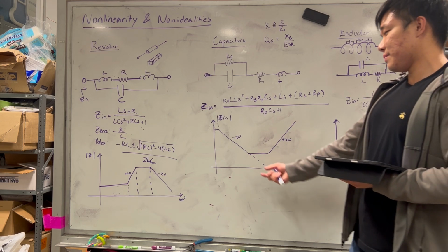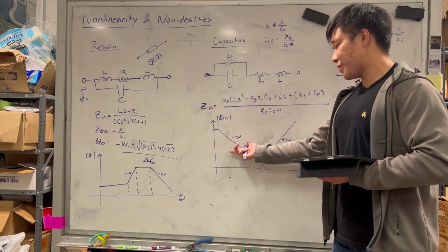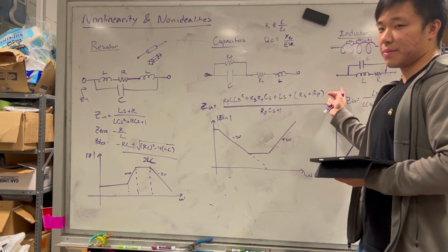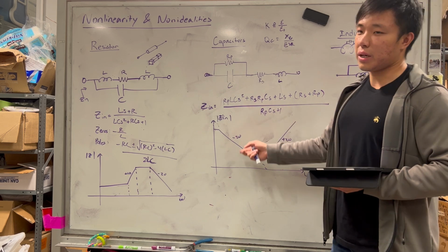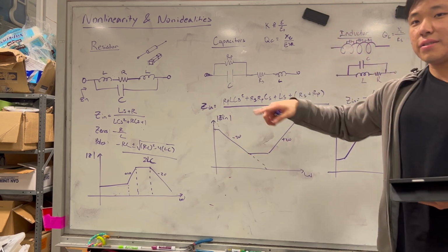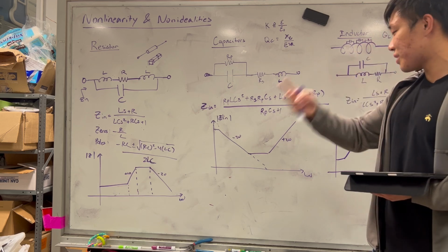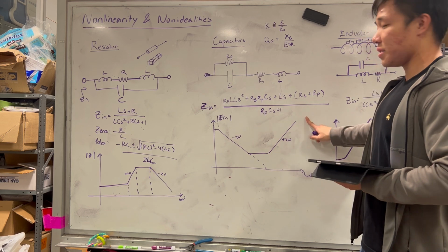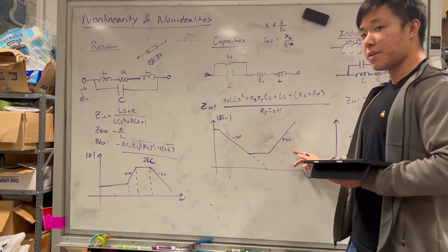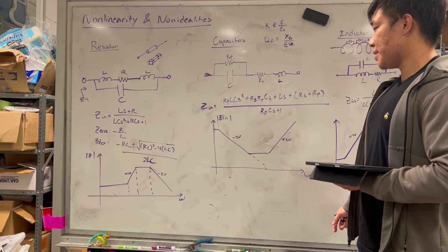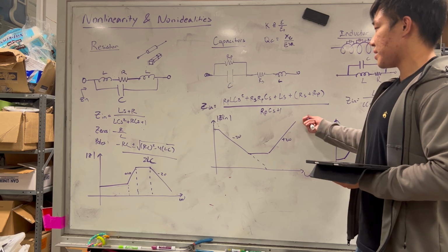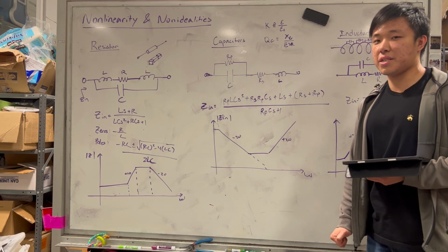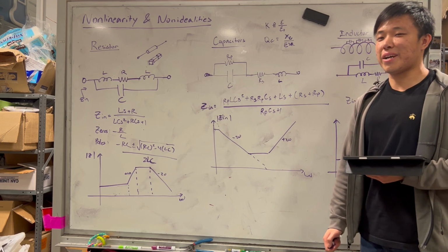But as your regions get more, how do you say, inductive here, right? So normally when you see a pole, what happens to the phase diagram? It goes down by 90 degrees, and this kind of goes back up to 0 and then back up to 90-degree phase, right? So you will see a phase shift here. The system's well behaved, so I'm pretty sure both of the zeros here are actually in the left-hand plane, so you won't actually see any crazy right-hand plane zeros.